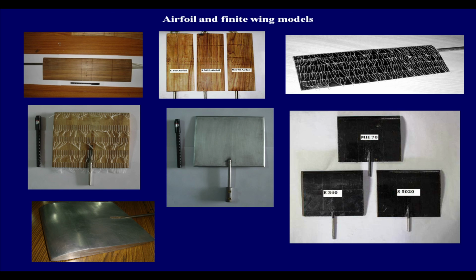The other part of the story is you have to be careful about surface finish. So, you have very minor ups and downs on the surface. How do they matter? You are tackling a viscous flow. So, you know that flow very close to the surface actually gets stuck in those minor undulations and tends to form small eddies, and tends to even drag upper layers and keep them slower.